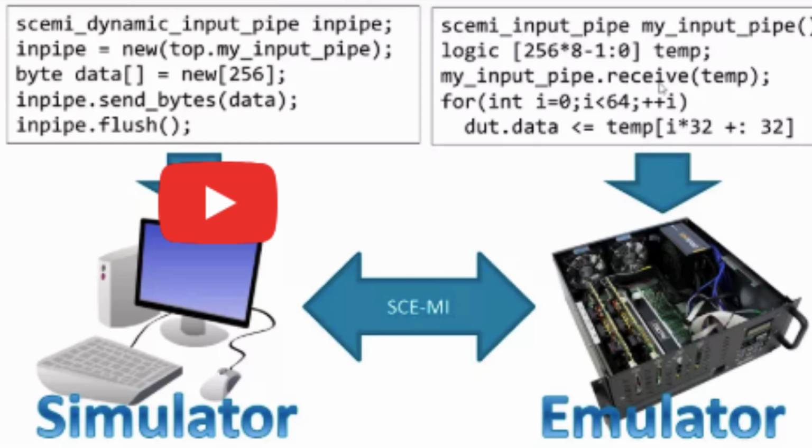Generally, verification engineers put a lot of those constructs in the Verilog language itself to do the chip verification process. There is no point in doing the actual synthesis with these simulation constructs. So that's why in emulation, certain portions of the design are sent to the simulator and certain portions are sent to the emulator.